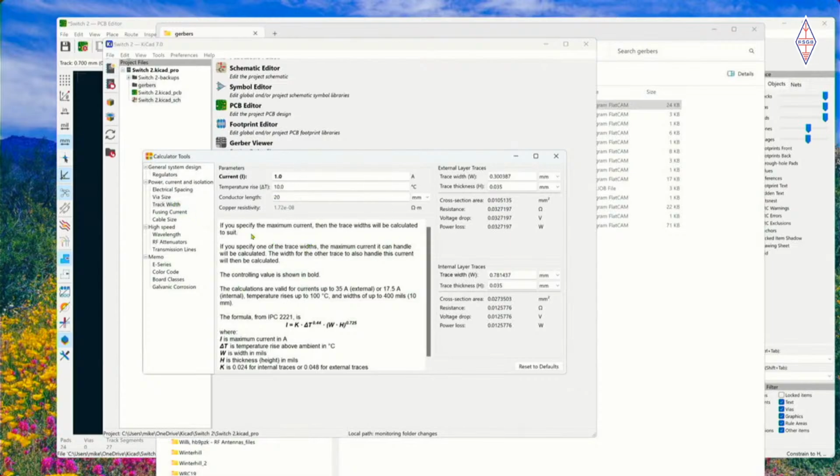So sometimes with a resistor, for example, most of us will know that resistors get rid of the excess by heat. So if we think that heat is going to get X amount hot, 1 watt or whatever, then this will help you calculate how big the piece of copper might have to be to help you dissipate or lose that heat. It can do that as well.